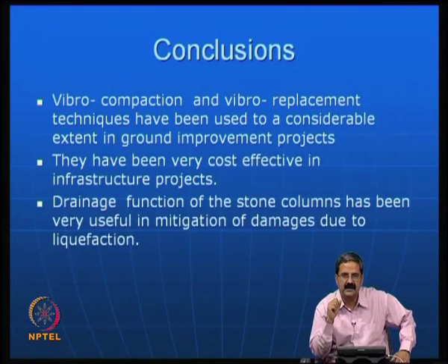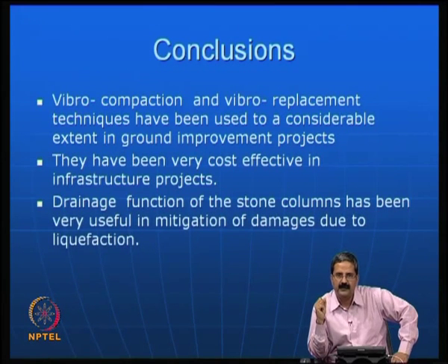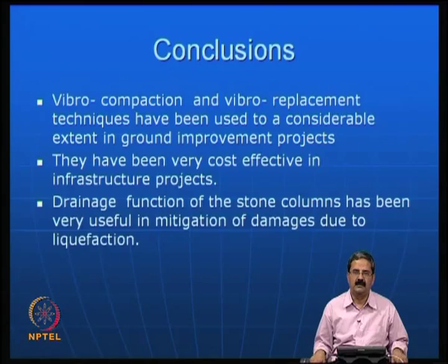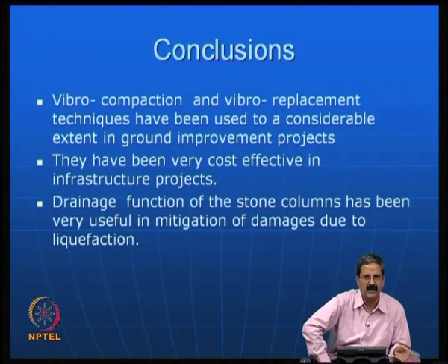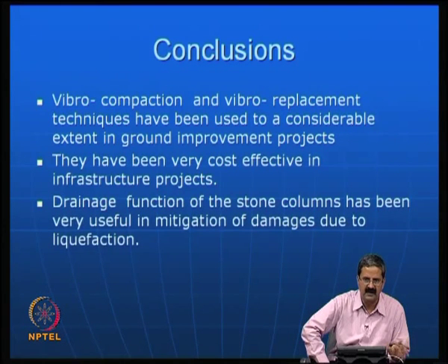In fact, in some places where they could not do anything, there is still no way, so you need to use ground improvement techniques. Then the drainage function of the stone columns has been very useful in the mitigation of damages due to liquefaction. In fact, in many places in Japan and other places where there is a major problem of liquefaction, this technique has been very effective and people have studied it very well.